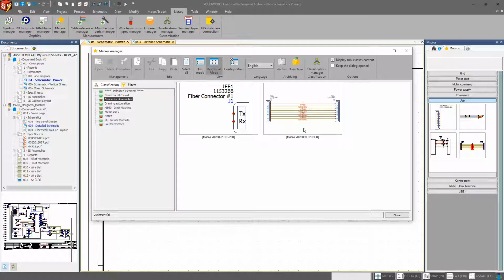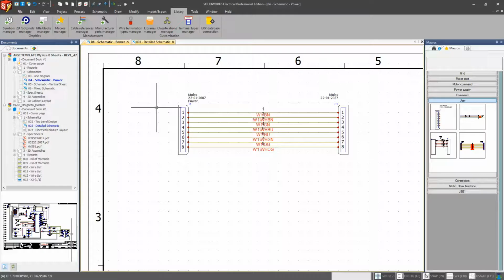If there's something on this macro that I'd like to change, I can very well select this macro and I can open it and I can edit and make changes to this. My recommendation is if you're using this circuit for an existing project or a finalized project for that matter, I would recommend making a copy of that macro and editing the copy. That way you always have that original macro that is in those finalized versions of projects that you've already approved for build.